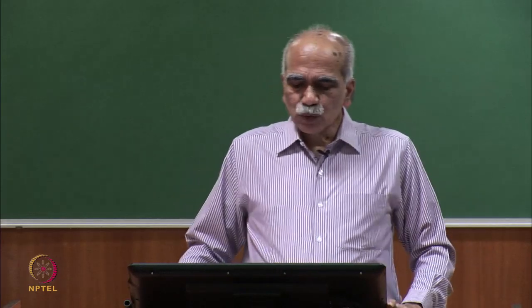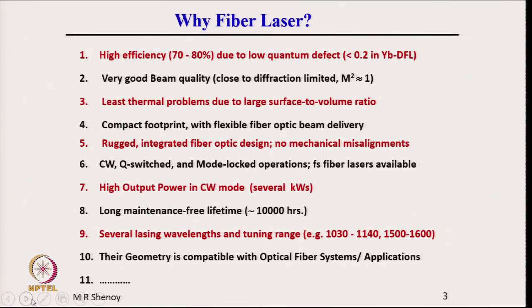So, the first question is why fiber lasers? There are n number of reasons. I have listed some of them here. Very high efficiency. Efficiency here refers to the output power divided by the pump power. So, P out at the laser wavelength divided by P pump. This is defined as the efficiency.